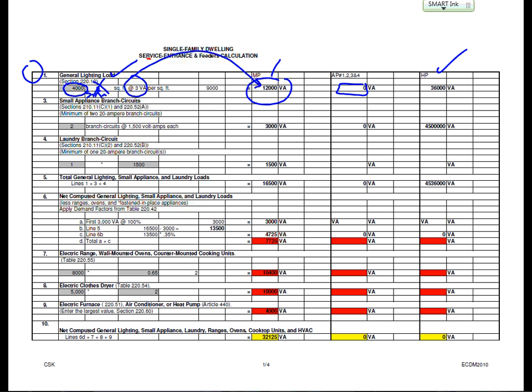Can I get thumbs up, chat, that we're doing the 3 calculation? So you're going to take the square foot of the whole building, that'll get you this number. Then the square foot of the apartment, that will get you this number. And also another square foot for the common, and that will get you this number here. One more time. You take the square foot of the common area, multiply by 3. That will go under the common panel, the house panel. The square foot of the single apartment, the largest one, multiply by 3, gets you the number under the apartment. And take the whole building, top and bottom, 2-story. The square foot for the whole building, multiply by 2, and that will get you the main panel.